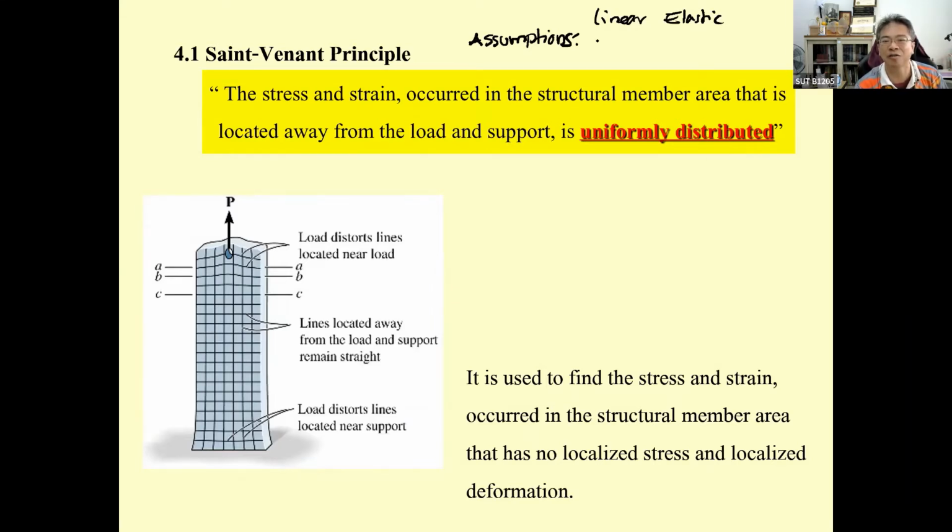Okay, and also we consider the deformation. And again, if I'm talking about this, the maximum stress must be less than or equal to sigma allowed, and the maximum deformation is going to be less than or equal to the allowable deformation. And there is one more thing about the assumption based on the Saint-Venant principle.